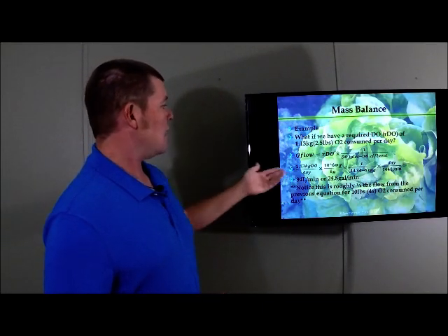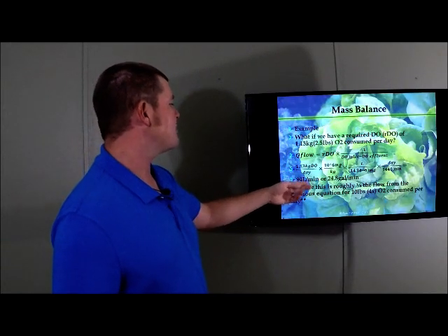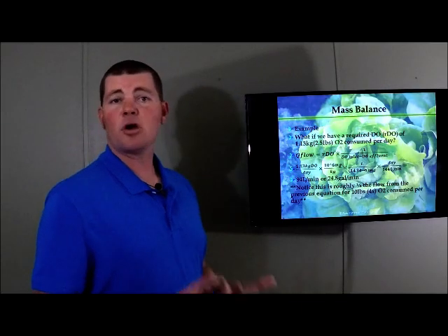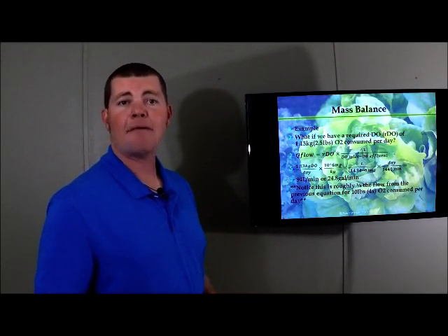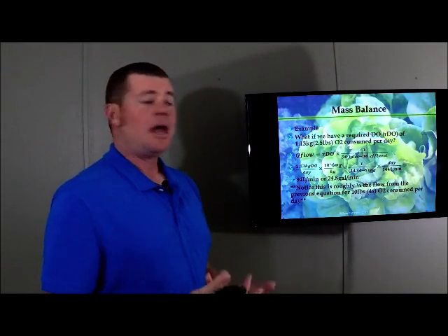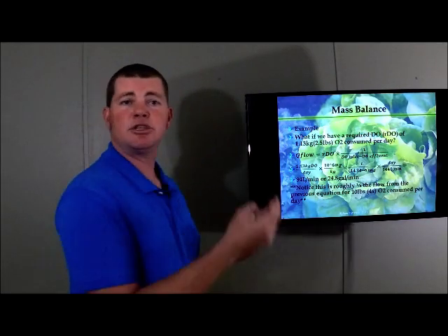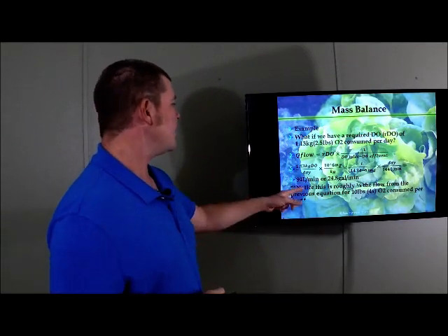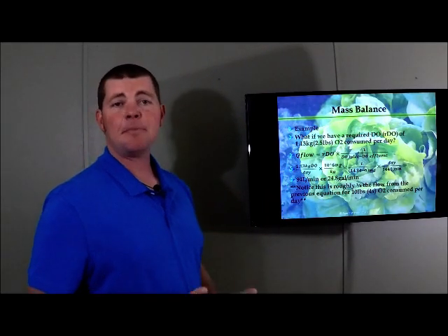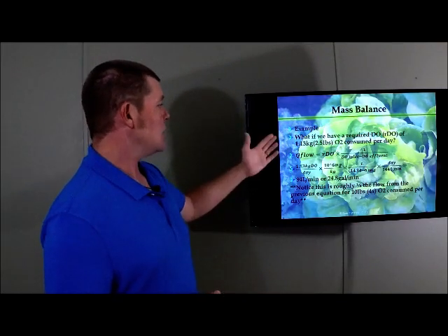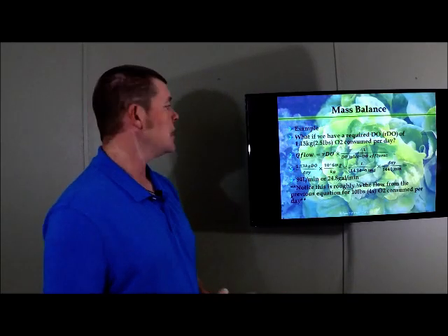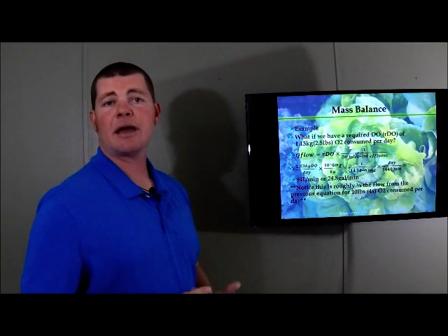We do the math there, and we end up with 94 liters per minute, or 24.8 gallons per minute. So that's the required flow rate that we need to have to actually sustain the dissolved oxygen that we want. And this is directly related to the equation we just did during the last slides. If you'll notice, this is roughly 1/4 the flow from the previous equation for 10 pounds of oxygen consumed per day. So it's 1/4 the flow because we have 1/4 the oxygen consumption. We have 2.5 pounds.